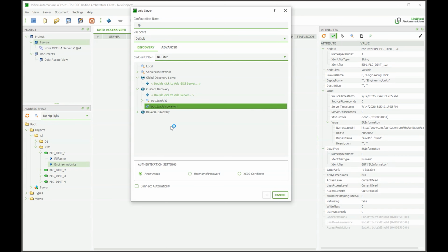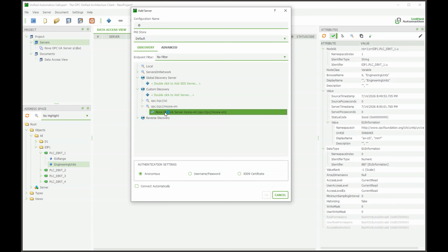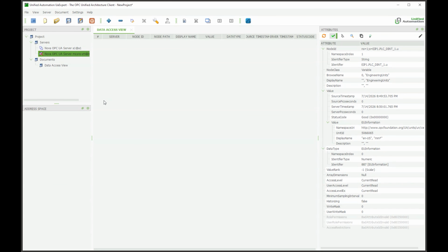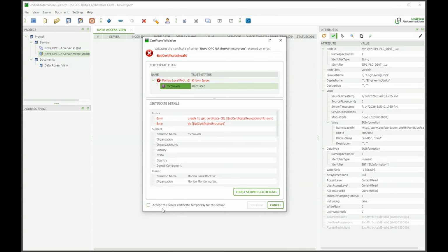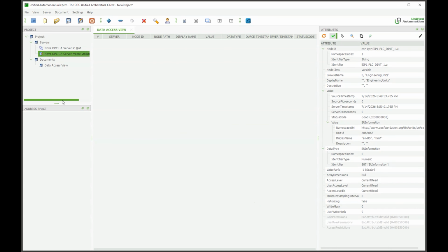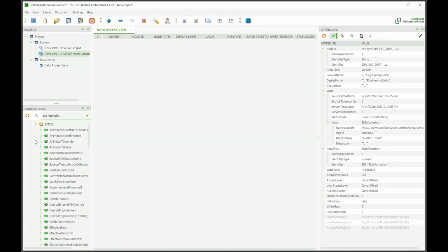And if I go to the OPC UA server that is on there that is configured to use this new advanced mode, I can connect to that. We'll do the little certificate thing. And then we'll be able to see all of those data values. And that driver is a bit special because that driver, like our J1939 driver, for example, knows already what the units are and what the engineering range is.